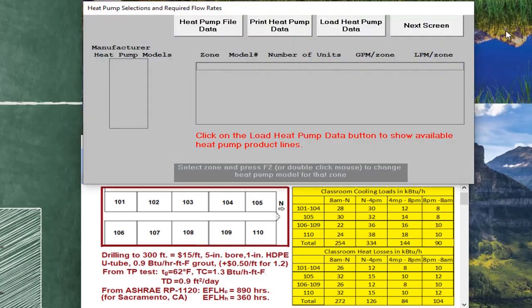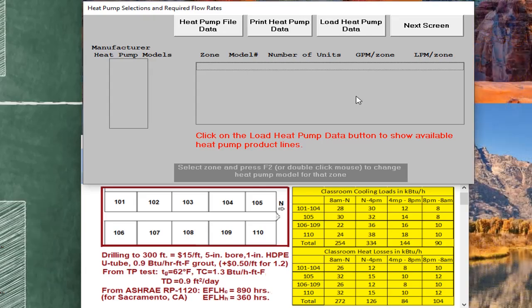This screen contains a lot of information from equipment manufacturers, a series of heat pumps, and these heat pumps have been corrected from their rated values to values that are experienced in the field. Two of the things that are important are the return air temperatures are rated at 80.6, which is not a comfortable condition, so we'll change the performance using an entering temperature in cooling of 75, and we'll use 70 degrees rather than 68 in the heating mode.